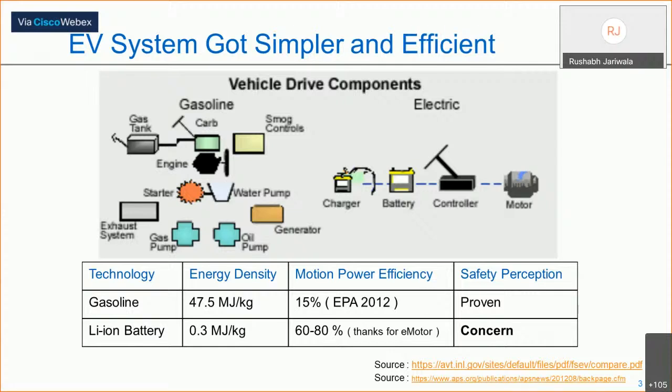Because what we are dealing with is the next generation of vehicle, with almost 400 volt DC, or even up to 850 volt DC HV battery, and some HV loads like the inverter and DC-DC converter, which are directly driven from this. So from a safety point of view, it is a bit of a concern.